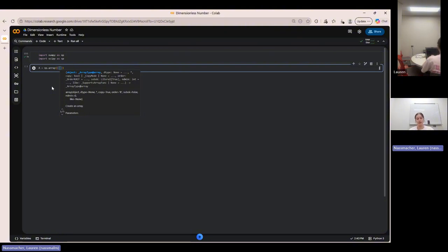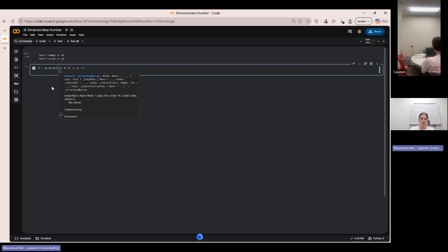Instead of velocity, pressure, length, diameter, viscosity, and density, I'm going to rearrange it so that the variables with the fewest number of units are in the front and the most in the back, like from left to right, least to most. So length and diameter, then velocity, then density, viscosity, and pressure. Our first row is kilograms, so our length and our diameter do not have any kilograms. Our velocity does not have any kilograms, but our density, viscosity, and our pressure do. Comma, next row, it's going to be our meters. Our length, diameter, and velocity have meters.